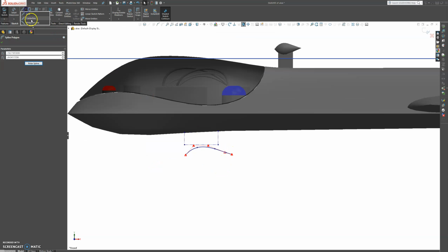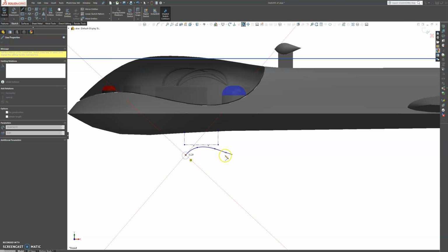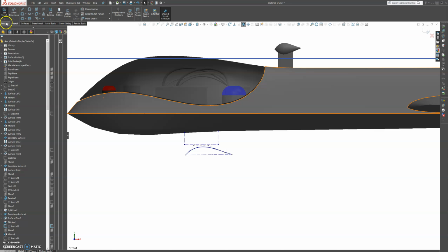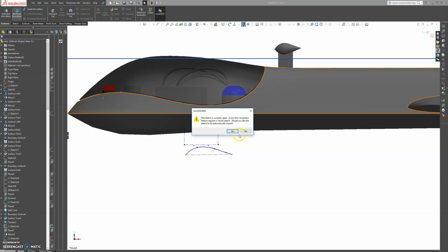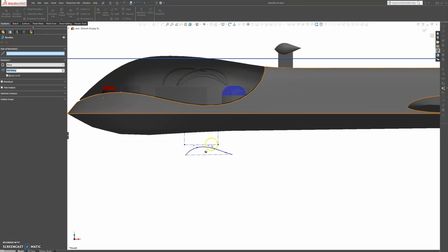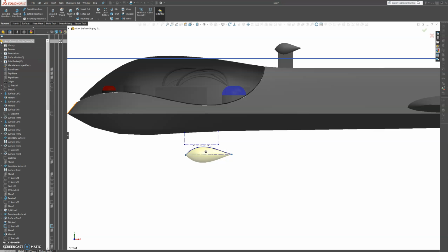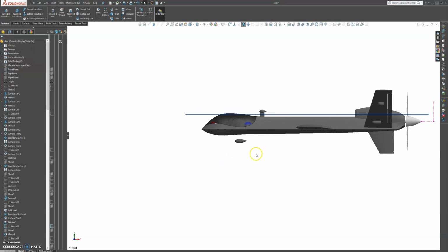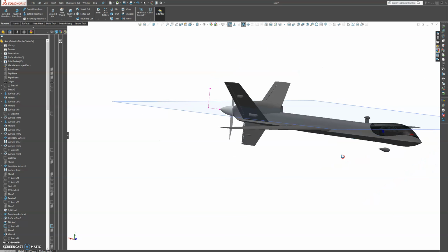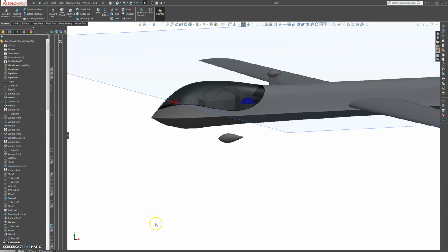Okay, let's say the center line in the middle here. Let's revolve this around and see what we get. Yes, close that up. Choose this line. And that looks good to me. It got a little bit bigger, so we will go back onto it and adjust the lines to make it similar to that one. So see you back at the next tutorial.